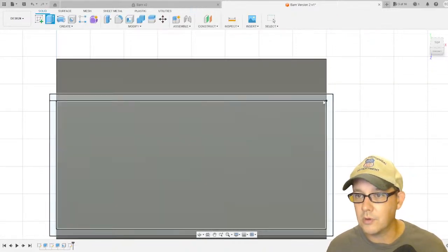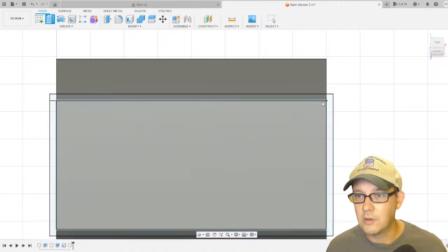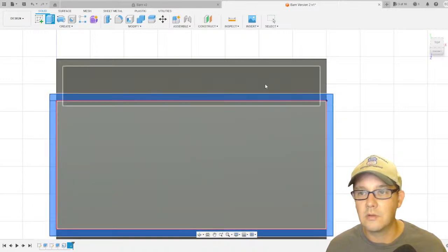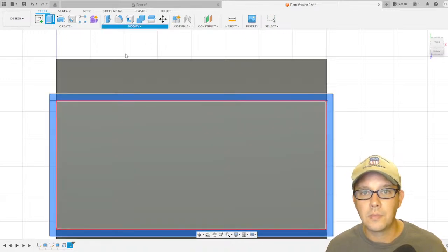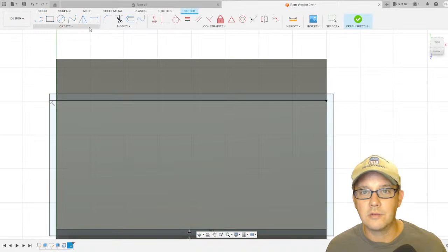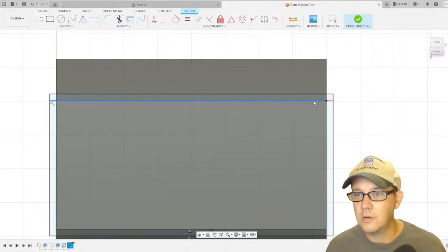I'm going to take this one, and I'm going to see if I can extend this. Oh, you stinker. I'm going to go back in sketch mode. Extend. There we go. That extends that.